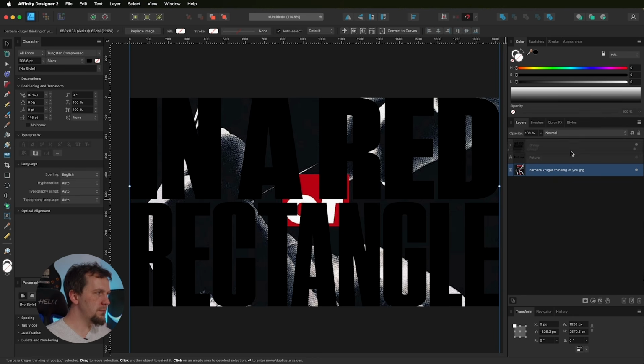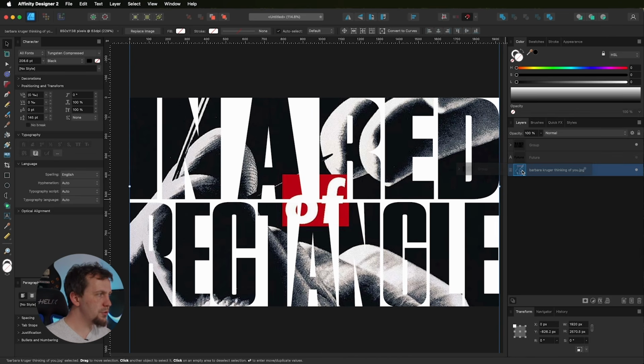Instead, I'm going to keep the text grouped, and I'm going to use it as a mask on the image instead. To add a mask, all we have to do is take the text, and instead of dropping it on the layer like we've been doing to clip, we're going to drop it on the layer's thumbnail. And this is kind of a crucial difference. Now, instead we're using the text as a mask. We can have multiple masks on one single image.